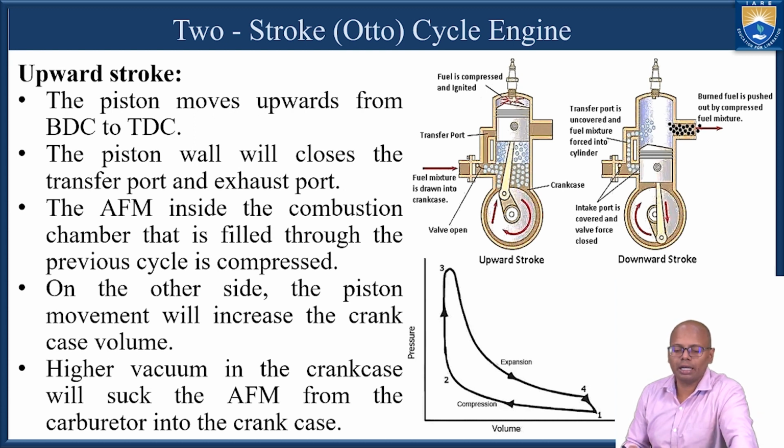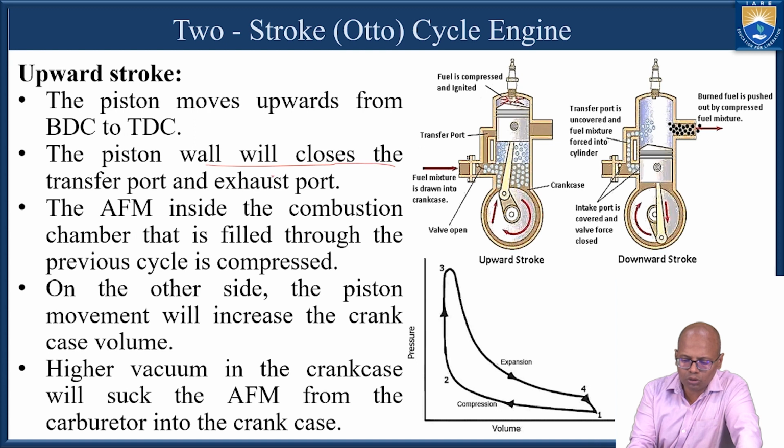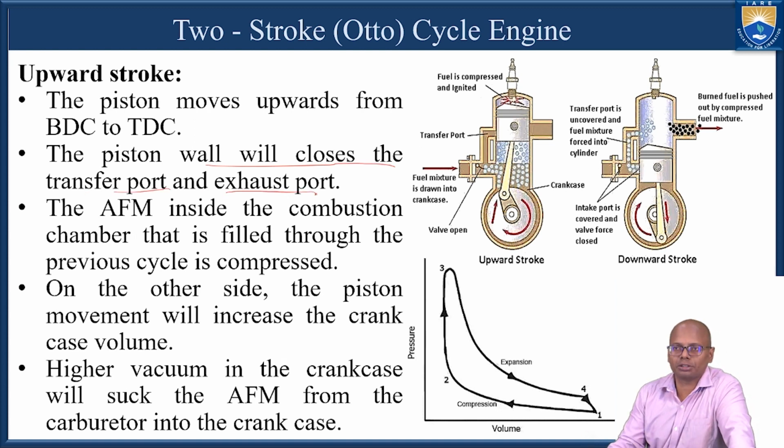So what is the upward stroke? The piston moves from the BDC to TDC. What happens during this? The piston closes the transfer port and exhaust port.